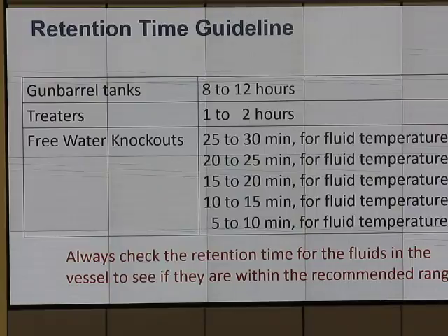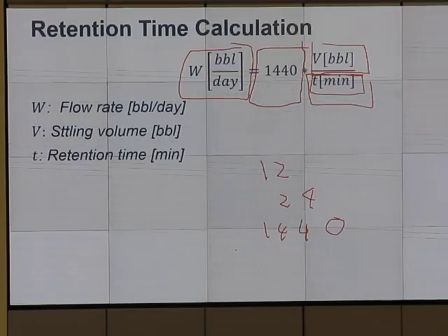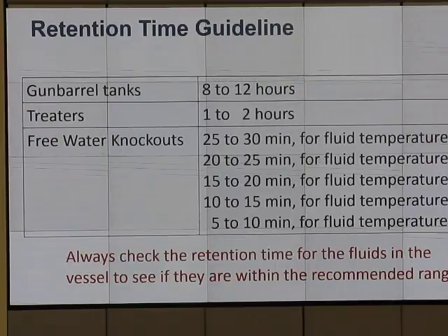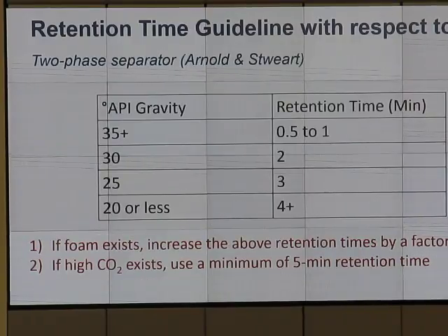Retention time in the treater gun barrel. So this is a suggested retention time. How much should that be? If you go back to use that equation, make sure that the units are consistent. And the part that I pointed out is for free water knockout, you can use less retention time but have to heat more. We talked about this, right? Yes, we did. And there is also API gravity and retention time for the gas liquid separator.